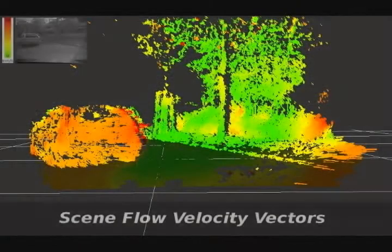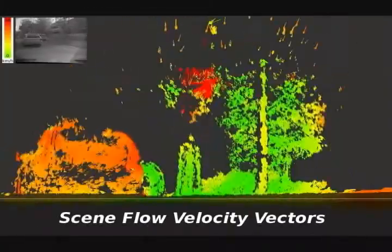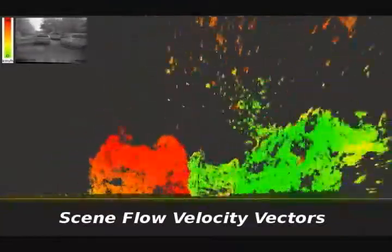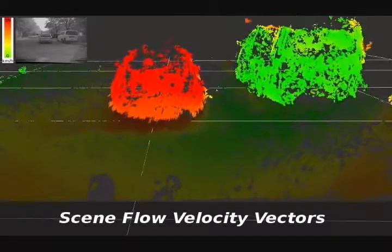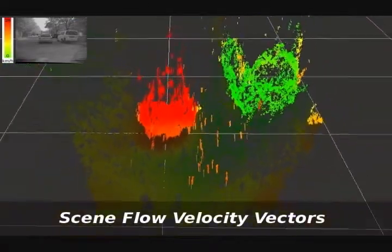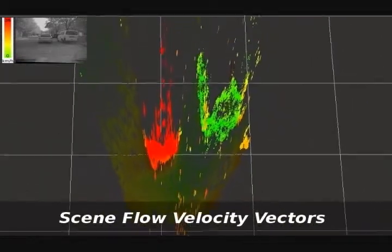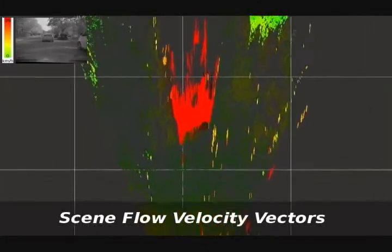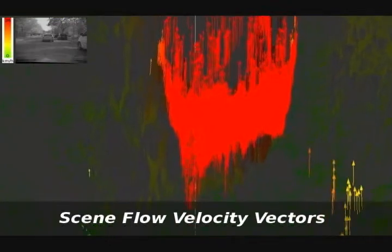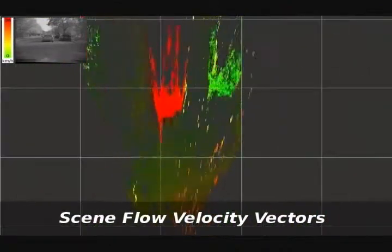Here is our final video showing a typical scene where we are following another vehicle. A speed of 0 is shown as green and a speed of 36 km an hour is shown as red. The original video can be seen in the top left corner. The lead vehicle has vectors clustered together and depicting the same magnitude and direction. Furthermore, all parked vehicles are shown as stationary as they should be. If we zoom in on the car from above, the vectors can be seen shown similar magnitude and direction. No post-processing has yet been conducted on these results.